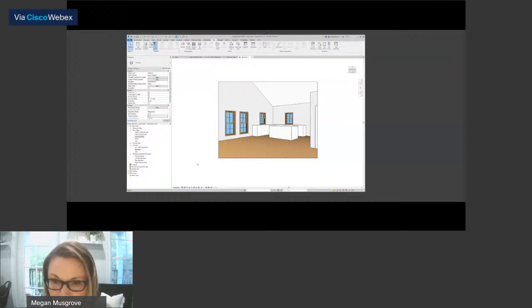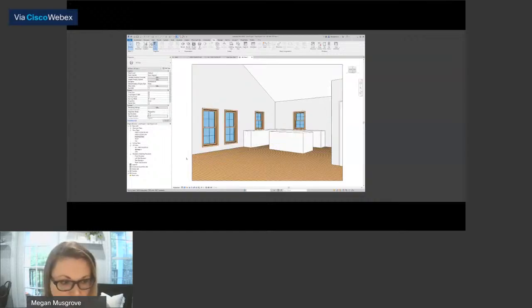So we're going to do a couple more things before we wrap up for the night. If you see over here in your project browser, it named it the default 3D view 1. Okay. If we keep creating views, it's just going to start numbering them down, and we're not going to have any clue where we are. So we're going to rename this. I'm going to slow click on that, and I like to differentiate my exterior and my interior.